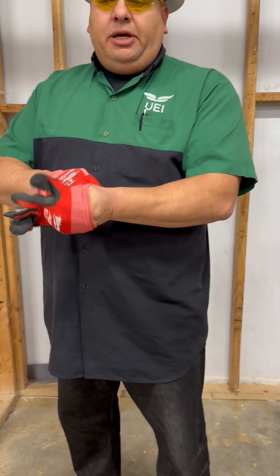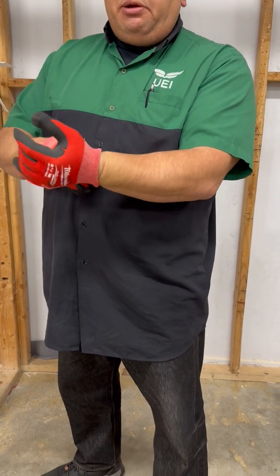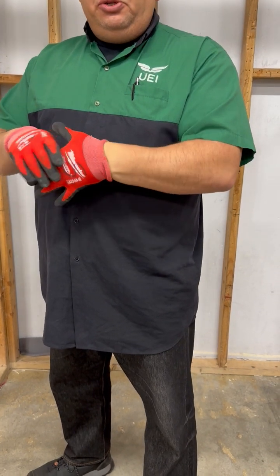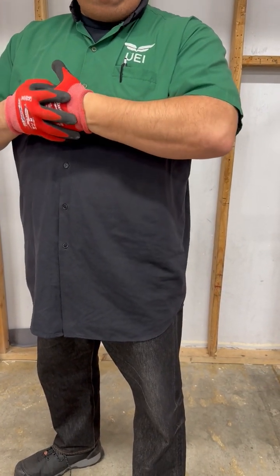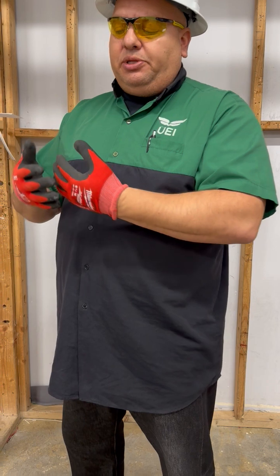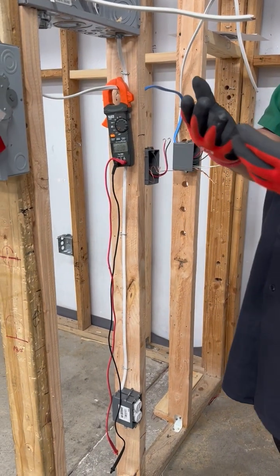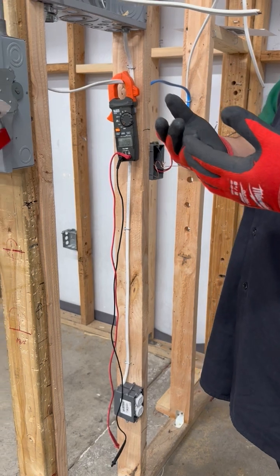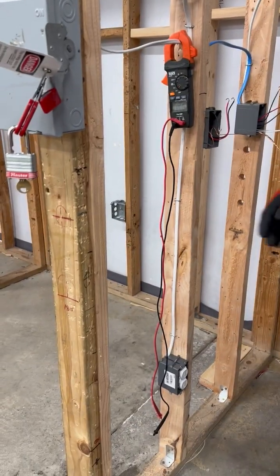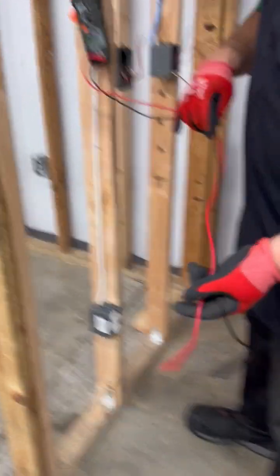I don't care if we're moving material around or picking up trash, as soon as you get a puncture on one of these gloves, they're no longer going to protect you electrically. And there's also a fabric back end. If you want to be protected, utilize the leather gloves. They're more durable and will withstand punctures or scrapes.